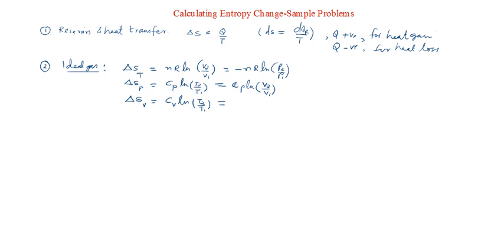So already we have taken volume constant, and so the variables are temperature and pressure. So it will be Cv log P2 by P1. Just have a close look at the symmetry of the equation, which will help you to easily recall. Wherever there is a pressure involved, there will be Cp here. Where there is a volume involved, there will be a Cv here. And when it is temperature, it will be nR here. All other things are very similar.